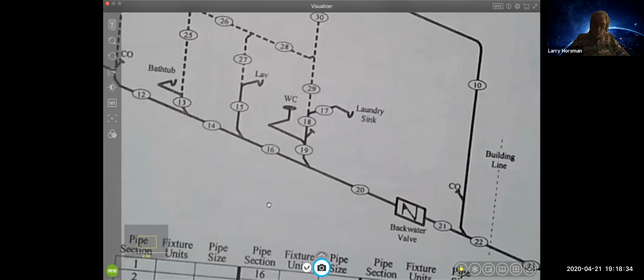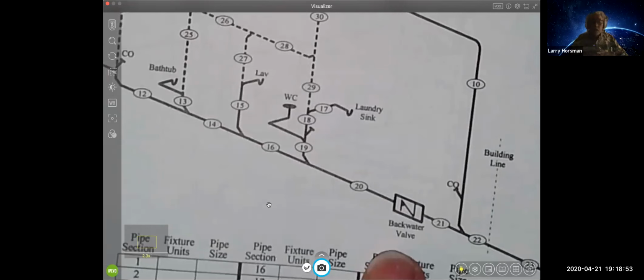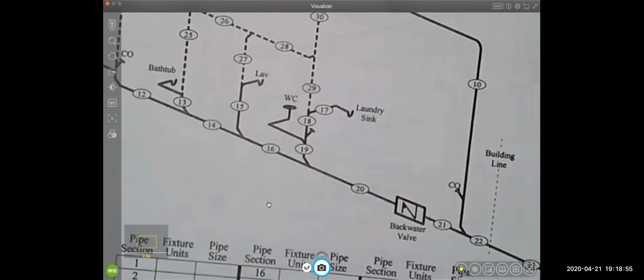If sewage backs up in the manhole, then you have a head of sewage. Then you may go from being above the sewer line to below the flooded manhole rim, and sewage can get back in the house. That's what a backwater valve is for, to take care of that particular problem.